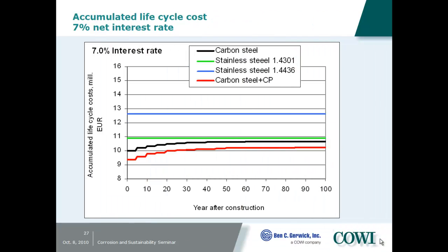And if we go as high as 7%, the cost optimum solution is actually cathodic protection in this case. So that's passive cathodic protection? That is passive cathodic protection or prevention. You can say the strategy where it's used after 75 years is still assuming that you apply it before corrosion has actually caused any damage. So it's still a passive system.